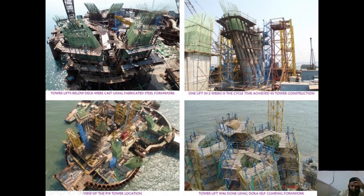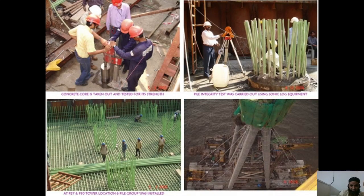View of the P19 tower location. You can see here the tower location. This is the top view, where the coffer dam had been erected, the piles had been casted, and the pile cap had been casted. Over this, the pylon has been installed. You can see here a concrete core is taken out and tested for its strength. Again, after casting, the concrete is also tested. You can see the integrity test was carried out using sonic log equipment.